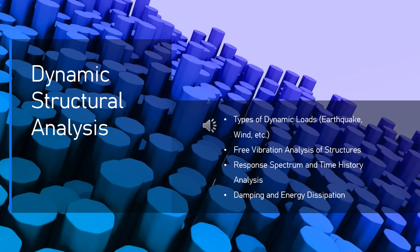Key parameters in free vibration. 1. Natural frequency: the frequency at which a structure naturally tends to vibrate when disturbed. It depends on the mass and stiffness of the structure. 2. Mode shape: the shape or pattern of deformation that a structure undergoes as it vibrates at its natural frequency. Each mode shape corresponds to a specific natural frequency.